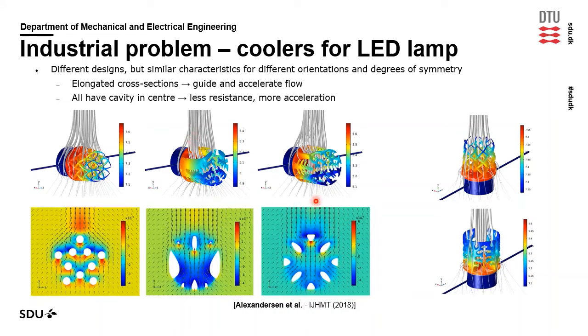Whereas for the topology optimized design, we get much more open, streamlined designs that draw air in and out where it is needed. And we see the true purpose of these hollow regions in the middle are actually to provide the air a chance to accelerate or at least move without further fluid resistance. So we keep a high velocity on the top members as well.